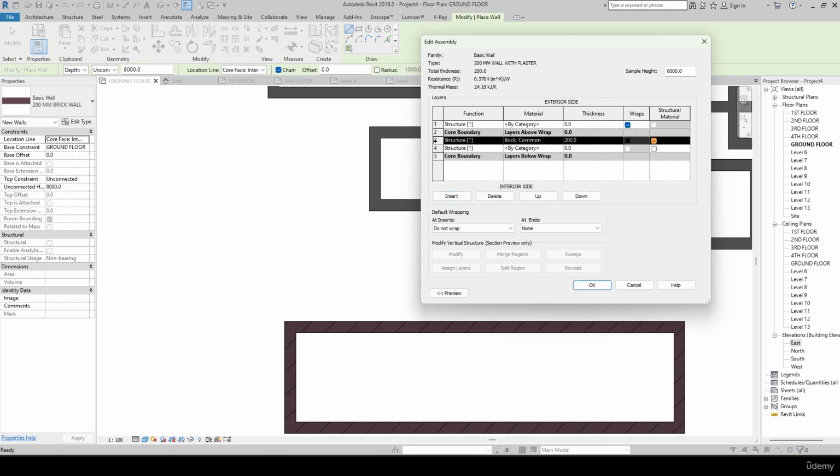So basically this is the structure. Column number 1 and column number 4 are the finishing items. Column number 1 is fine, it is being laid above the structure, but here it's overlapped. So I want to make sure that this has to come down. Okay, now this has been arranged, but I need to assign the value. What is the plastering thickness I want to assign here? Maybe I'll assume 15 mm. Then here as well I'll enter 15. This is the structural layer, and these two are the wraps or maybe the finishing materials.